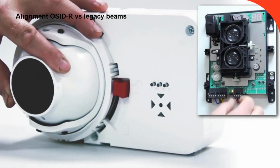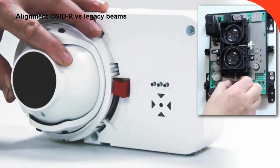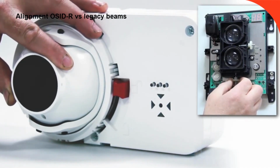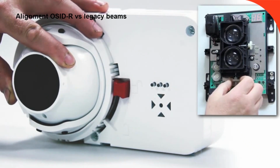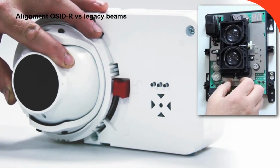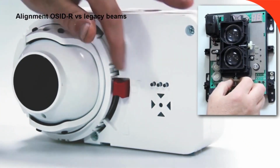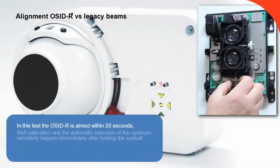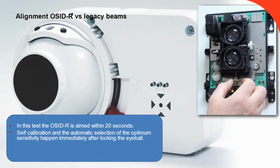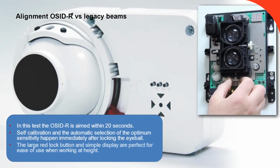OSID versus legacy beam devices. The OSID typically takes less than 60 seconds to align and auto-configure. A comparable reflective beam, the 6500 or 1224 in this case, can take many times as long and is much less intuitive, also requiring special tools to operate the micro switches and the addition of a lens cover which must be secured by screws before the configuration process can be started.